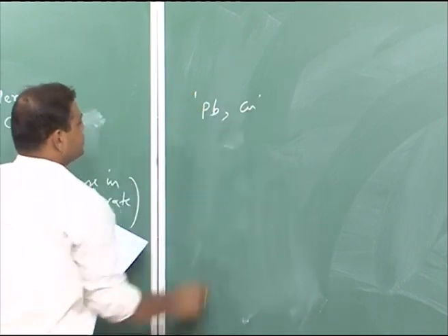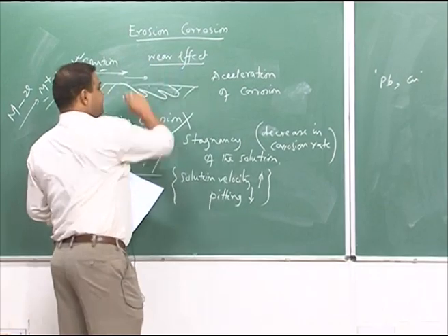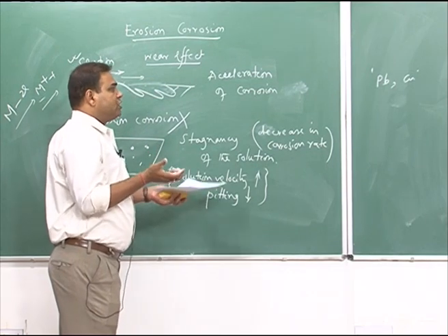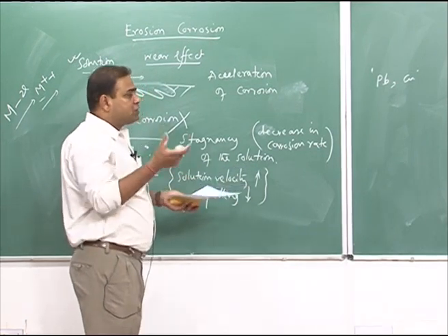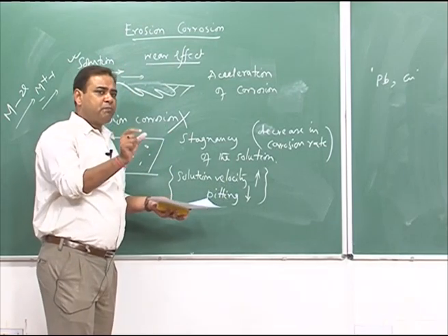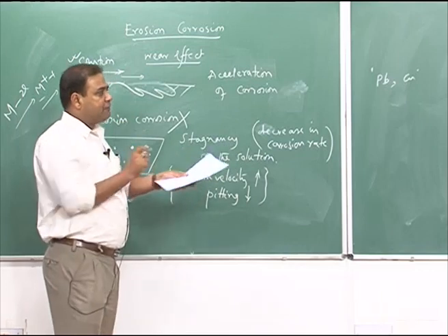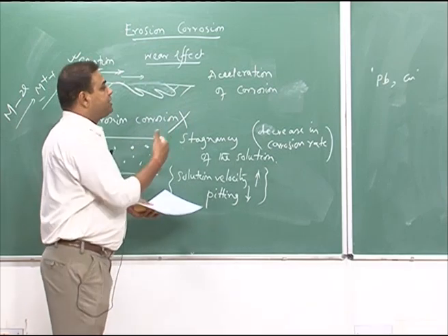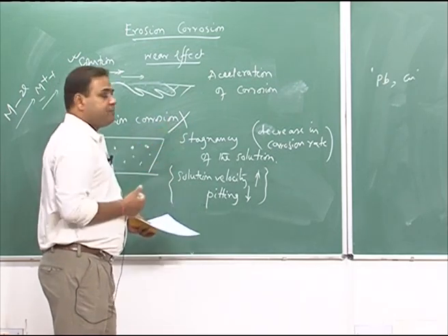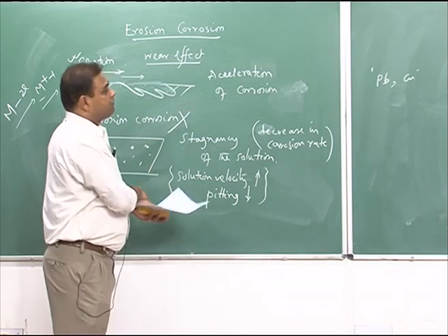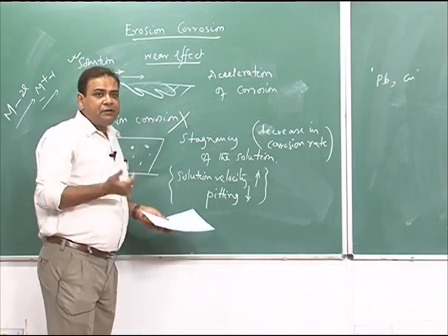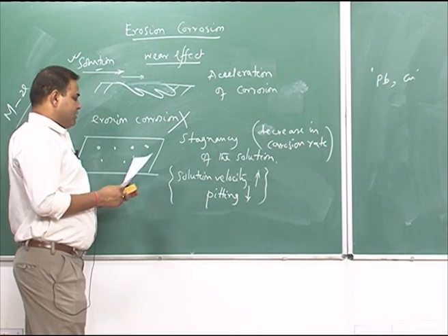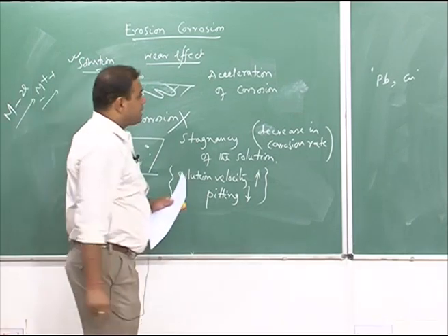or copper. The soft material, because of those erosion effects, there could be localized deformation, and that deformation could possibly form a local galvanic cell, because the deformed part and undeformed part could have a galvanic coupling effect, and so the undeformed part would dissolve quickly. Or there could be a possibility of a deformed part which becomes embrittled, and then that goes off because of the erosion effect or the movement effect. This is basically a dissolution of metal ion.